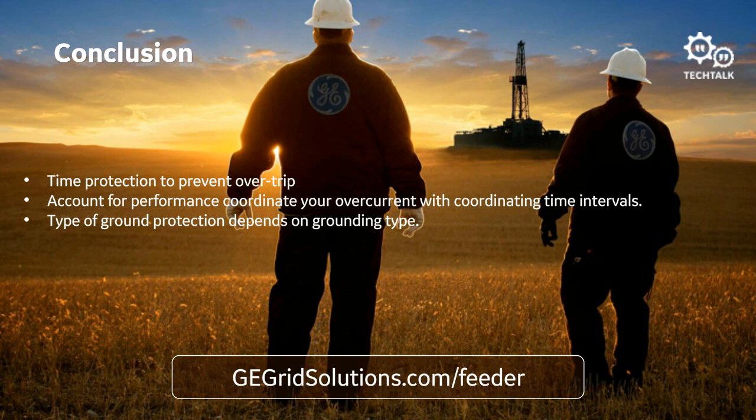A really cool hack that I usually use to figure out the trip times for a curve is, I mentioned the flex curves earlier, so I can go to any relay setup software that has a flex curve, like the 8 series or the UR, and there's a functionality in there to initialize the curve from a standard curve. So I could just pick whatever standard curve I'm wanting to look at, and click on initialize from that curve, and then it will populate trip times based on that curve. And that's a hack that I typically use to do that.